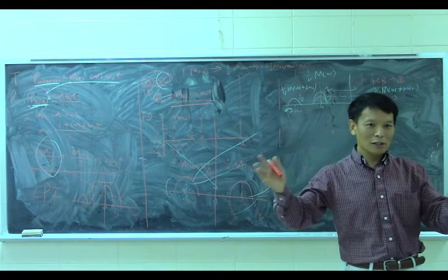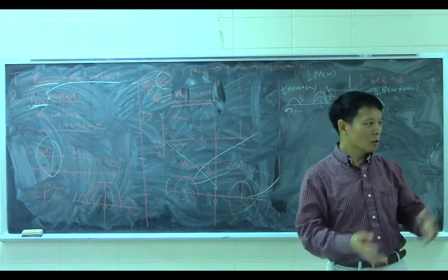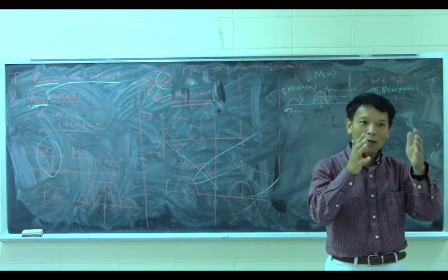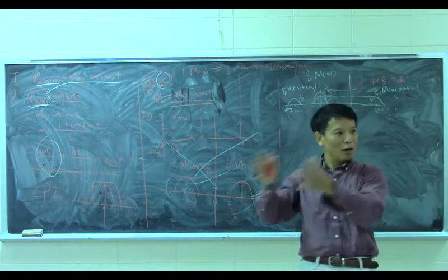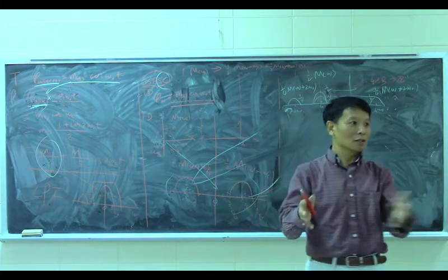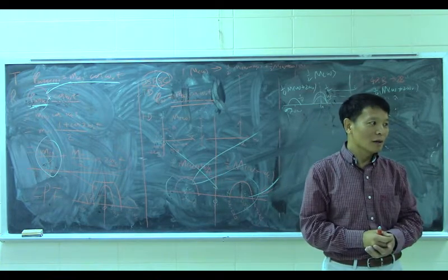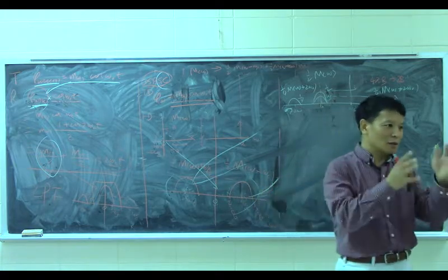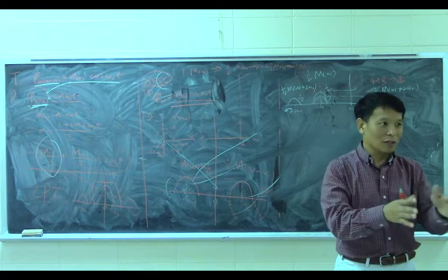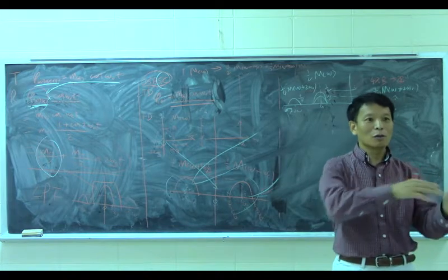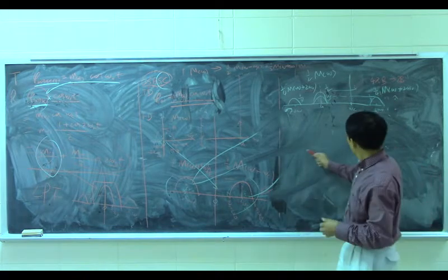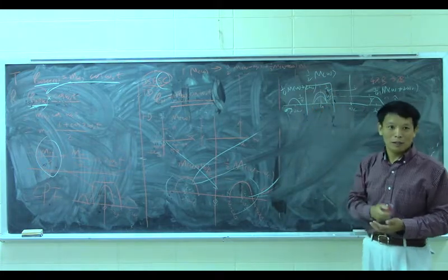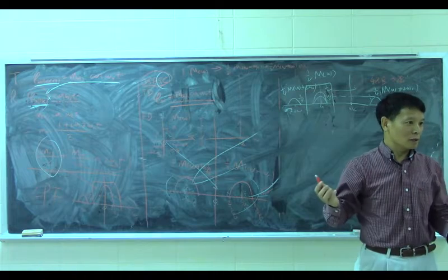How to explain all these things in frequency? So you have a baseband signal, that means you have a spectrum. If I can manage to shift this spectrum to a higher frequency, that is the modulation. And I shift this one to even higher, and some part to the center, to zero. Then I use a low pass filter, I get this one here. That is the baseband information. So that is a demodulator.